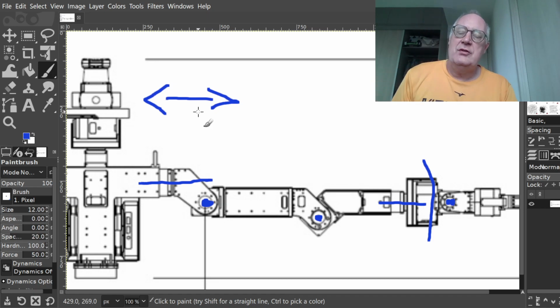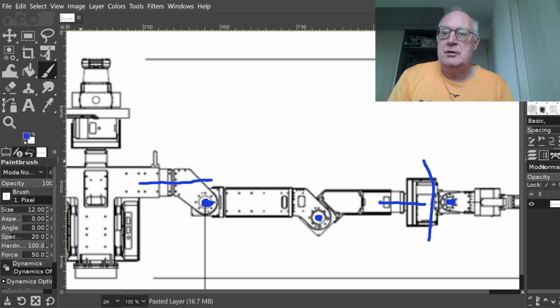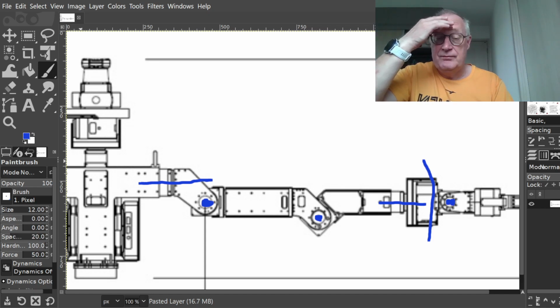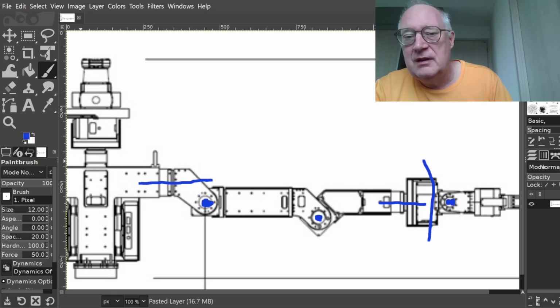Now that choice I can make freely, but when you think about that we're dealing with the servo motor, the servo motors are always in the default of most servo motors. Even though you can often switch it in software, if you take it out of the box, the default setting is usually that if you look at the servo horn with the motor, then the positive angle, the servo will rotate counterclockwise. That's just the convention that the builders have.